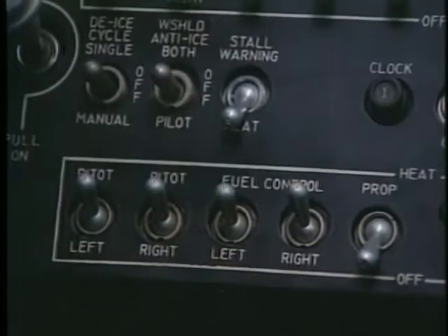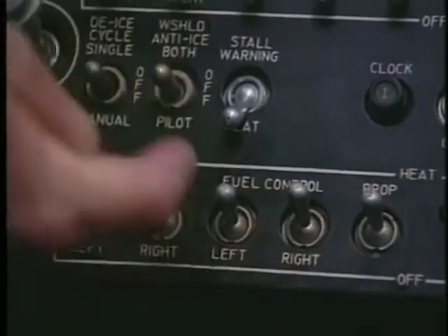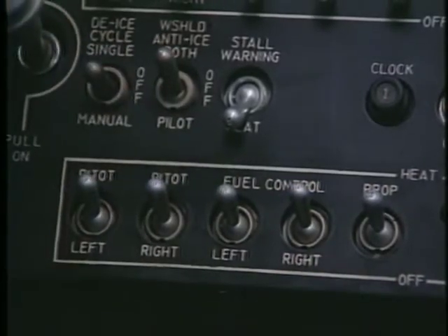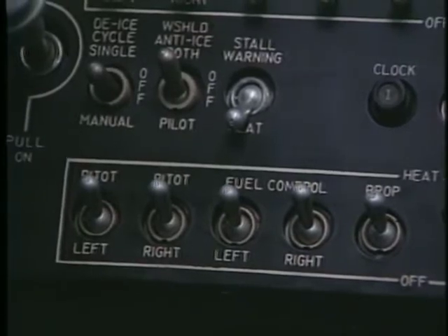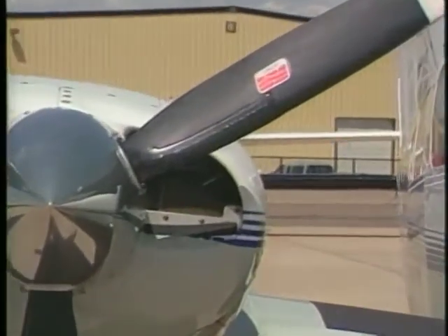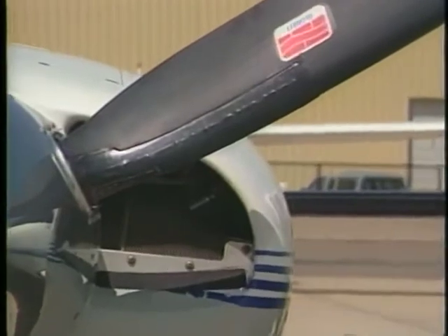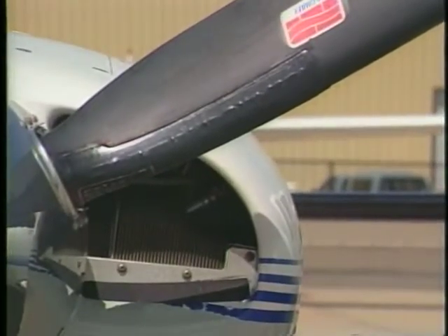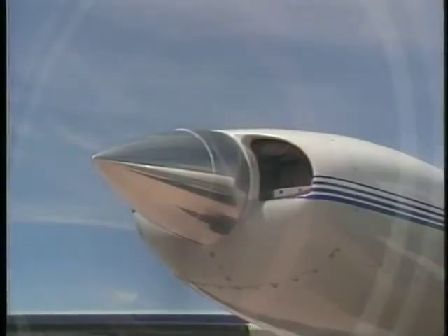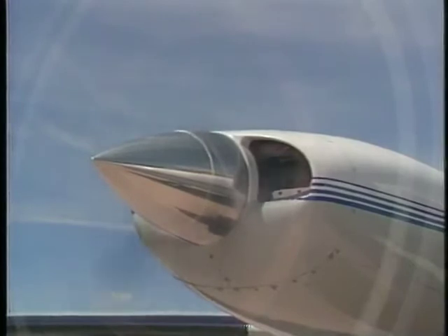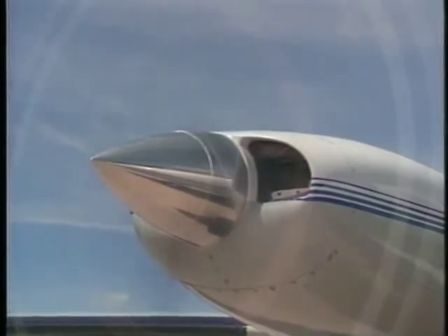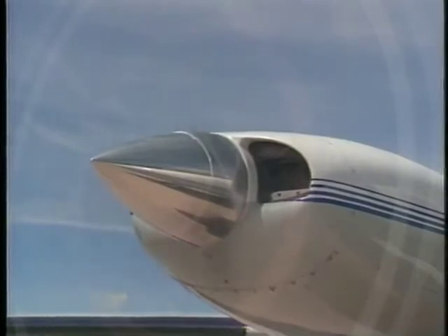Heat is also used to control ice on propellers and windscreens, but heated engine air is impractical, so electrical energy is used instead. Oil and wear-resistant pads embedded with electrical heating elements are bonded to propellers. Electricity is supplied to these pads through wire brushes in the propeller hub. Since centrifugal force is sufficient to throw ice off the outboard section of the propeller, the pads usually heat only the inboard section.